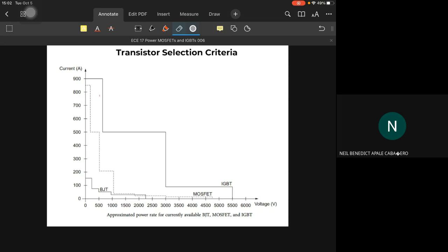But when we go to power electronics, not only are those parameters important, but also the fact that transitions will cause our electronic devices to dissipate power. So our objective is for our switching power electronic devices to have quick, or narrow, transition times.